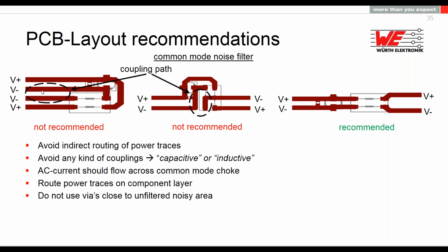but not enough. How about having the common mode choke with one side in and one side out? Avoid interference so close to the noisy area. Redesign number 2. One side in, one side out. Already this made it so much better, definitely. But this was still not the same effect as we had with the air PCB.